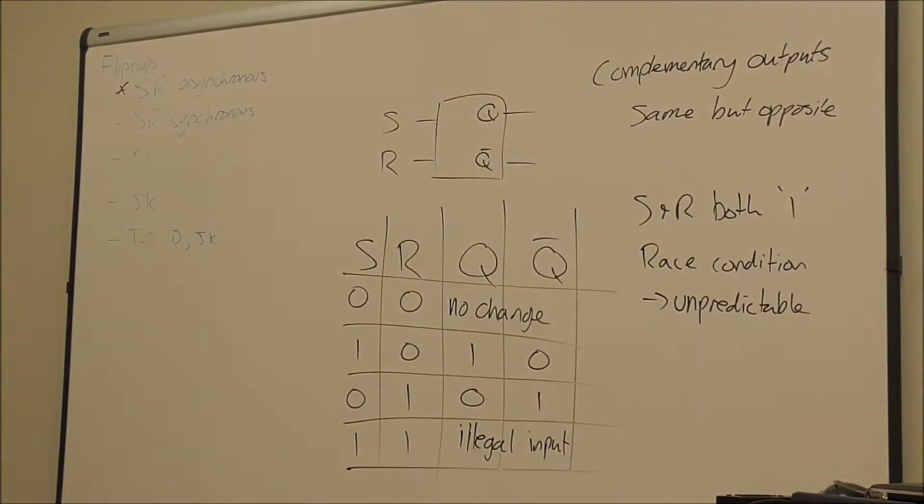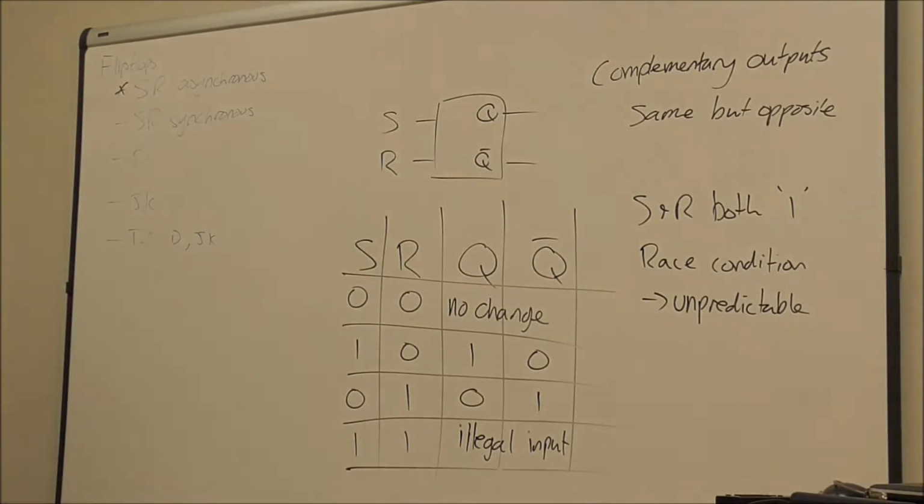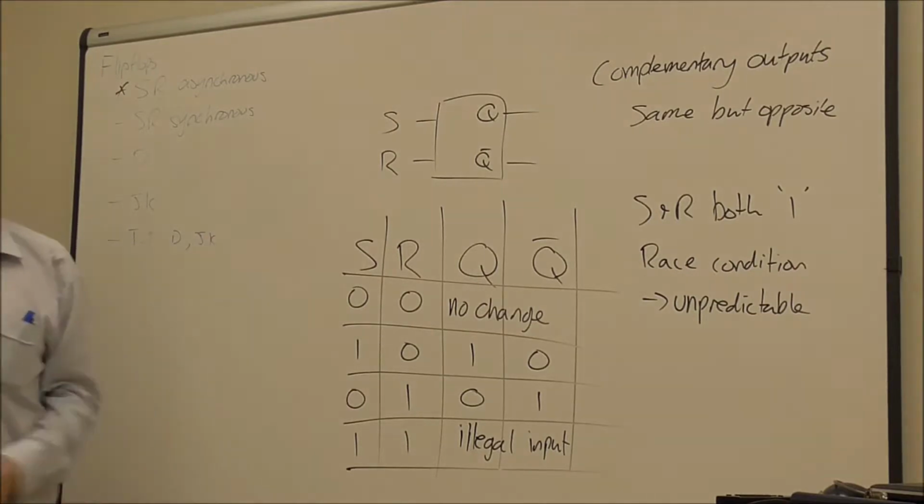And it might change. It won't always be the same for the same flip-flop. It might change depending on temperature, depending on some other variables. And also, it'll probably depend from flip-flop to flip-flop, things will be different as well. Okay? So generally we try and avoid that. And there are mechanisms in place that you can use so that S and R can never be both high. Okay?